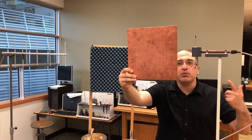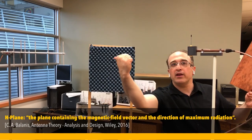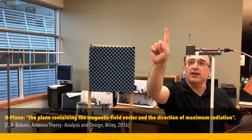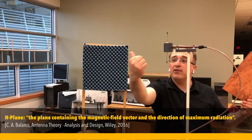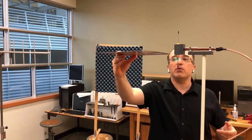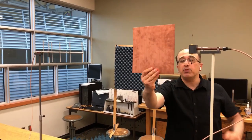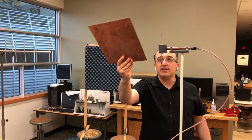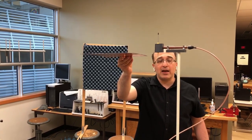When you go to the H-plane cut, you still consider the direction of maximum radiation in this way, and now your magnetic field H is perpendicular to it. That was E, therefore that would be H. So now you make a plane with the direction of maximum radiation and the direction of the magnetic field. This becomes your H plane. Again, to summarize, this was my E plane consisting of the electric field and the direction of maximum radiation. This is my H plane consisting of the direction of maximum radiation and the magnetic field.